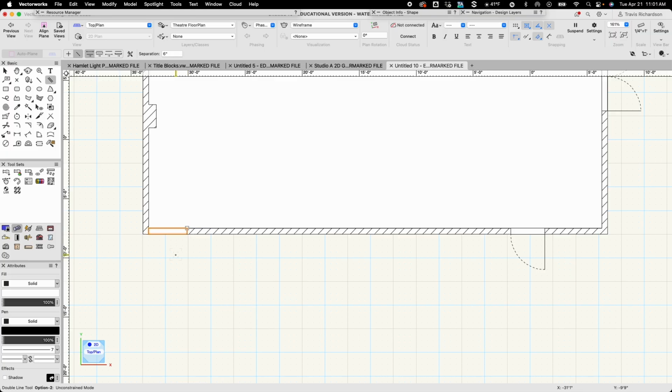And the door itself is also 3 feet, 4.5 inches. So rather than drawing another one, I'm simply going to duplicate this, Command D, and then I'll just grab the upper left endpoint and drag it over to the upper right endpoint. That'll be the opening for my door. I'll select the spacer and delete it. And then again, I need to draw my door and my arc.